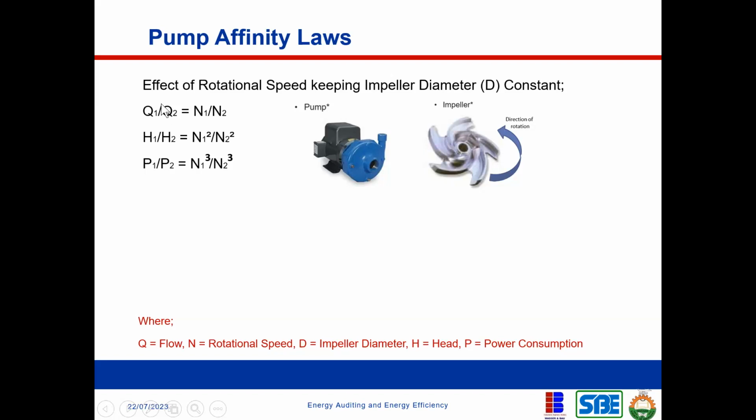Okay. So the quantity of fluid that is delivered is directly proportional to the rotational speed of the impeller. N is the rotational speed. I've defined all of those here. Q is the flow rate, or the flow of liquid or fluid. So the flow is directly proportional to the rotational speed. If the speed increases, you have more flow. It's just common sense.